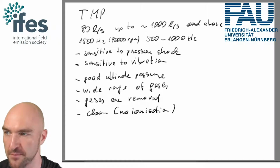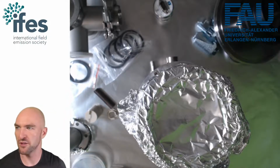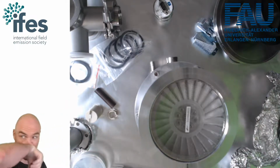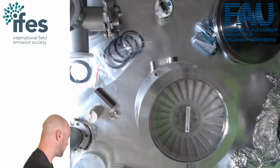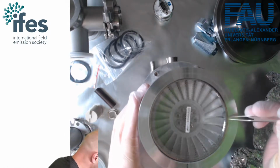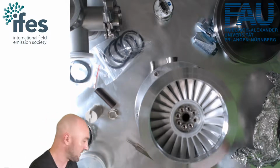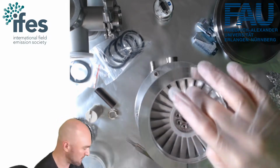I brought an older one here. A big thank you for the turbomolecular pump to our colleagues in Sweden. I got it from the group at Chalmers. It was on their old focused ion beam system, so it has an ISO-K flange instead of a CF flange. Obviously, if you want to have a UHV system, you want an ISO-CF flange. What you can already see here is that we can have some kind of inlet protection, so that if something falls on a turbo pump, it doesn't get into the pump.